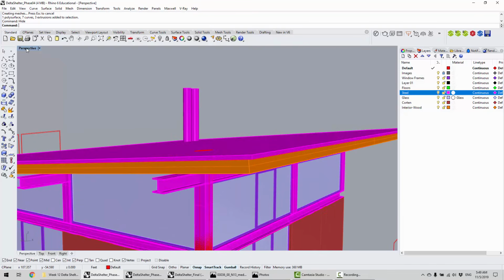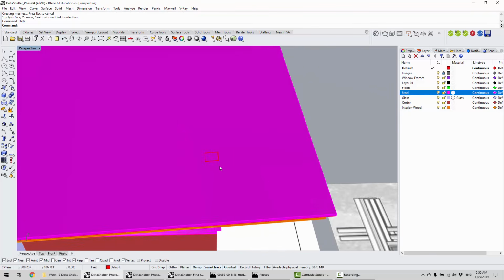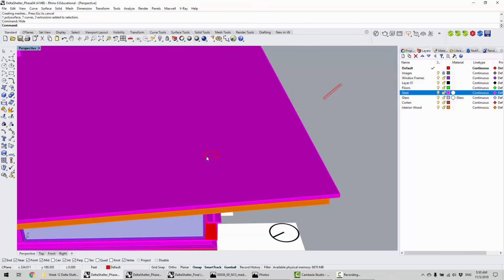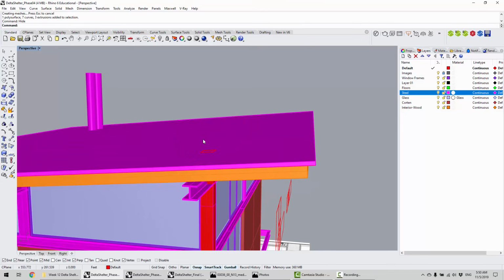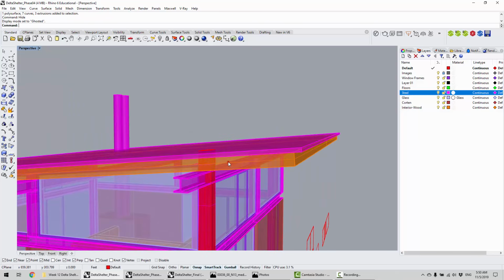Because sometimes when you trim like this and go to render it, you'll see the edge of stuff poking out because it's technically on the surface there. So to reduce the possibility for any sort of artifacts, what I do is go into ghosted mode and then do the trim again, basically taking it down.